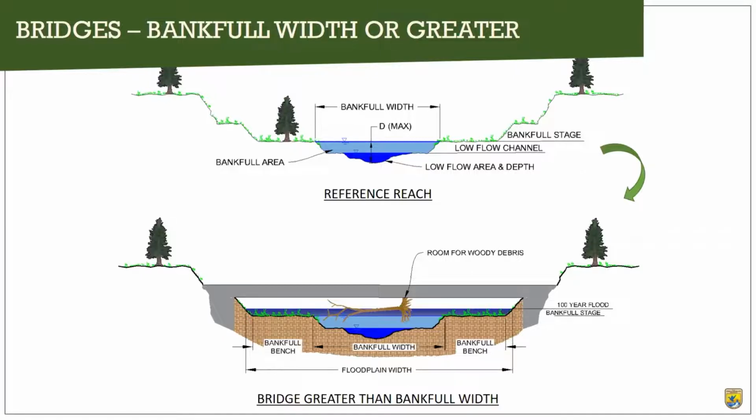And we're allowing for those depositional processes to happen because those flood flows are spreading out and slowing down and dropping out their sediments. So that's great for maintaining the vegetation, but it's also great for protecting your abutments and your bridge foundations, because you're just not going to see that scour process. You're going to see a depositional process.